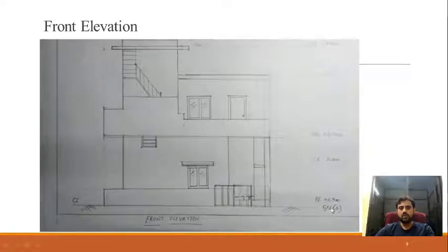Ground floor level is treated as 0 level, and this is the plinth level at the top, and this is the lintel level, and you can indicate the sill level also here. The bottom of the window is placed on the sill, so these can be marked out.